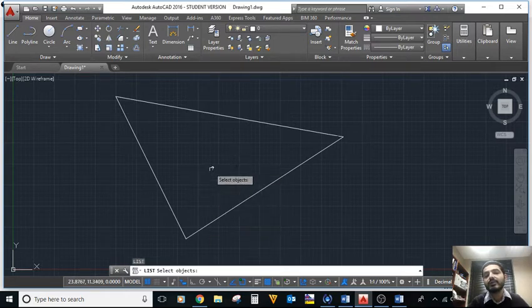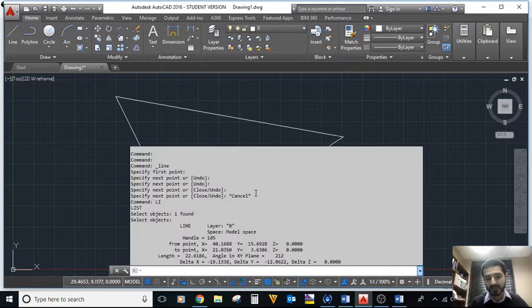As you can see, the mouse shape now changed to a question mark, and once you select that object, it's gonna pull out the properties related to that element. If you're interested in one object or more, you can keep selecting. But let's say I'm interested in one object, you hit enter, and now it's gonna open this up for you.